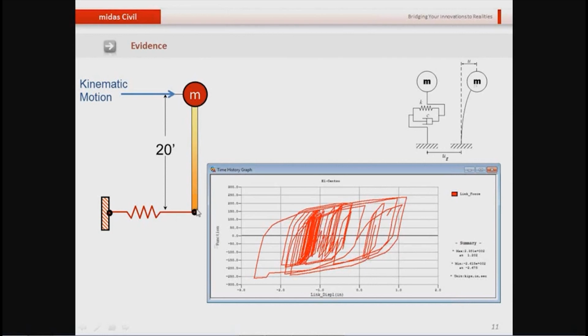So instead of imagining this as a column and then footing, you can consider this as a pile spring, and you can simulate this pile spring at different intervals along the length of the column or the pile member. But just to keep the analysis simple and straightforward, I have just applied it at the base of this column or footing, or column or pile.